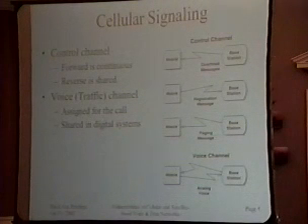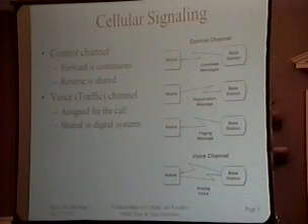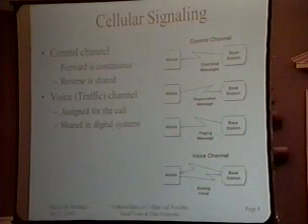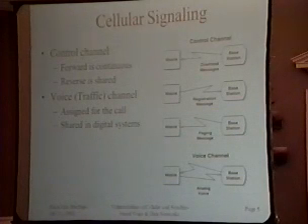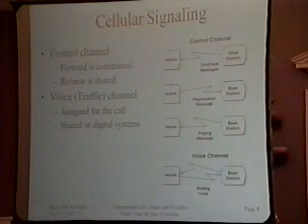Signaling, this will become important. When we talked about this in the last session, the base station transmits continuously on a control channel. It transmits what are called overhead messages. So a mobile, when it comes up, hunts for the strongest control channel and starts decoding those overhead messages. Those messages tell it who the system is, what the requirements are to gain access, those types of things.